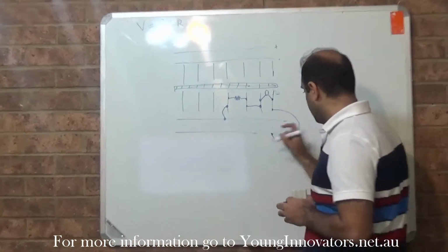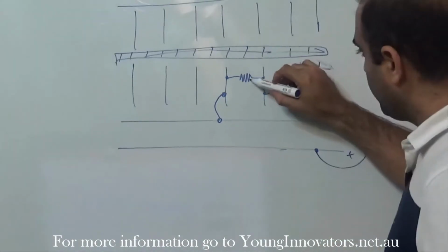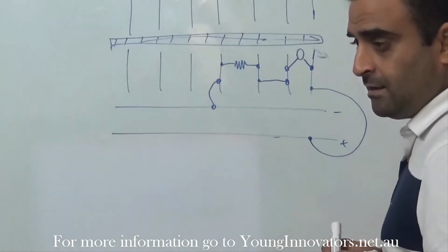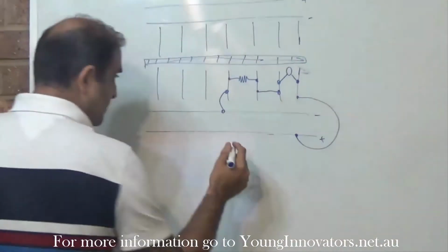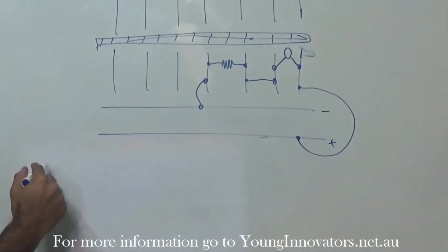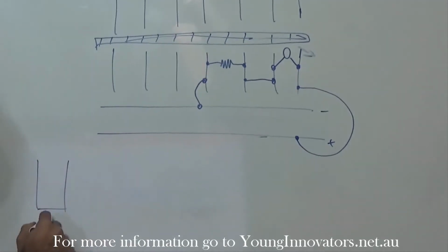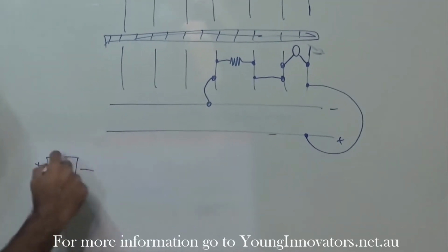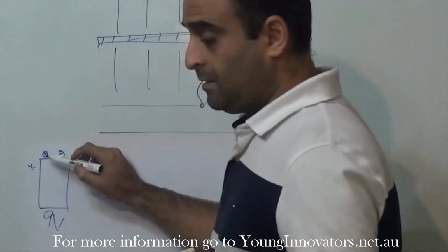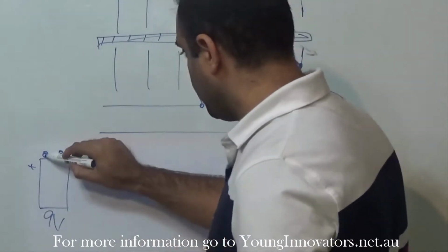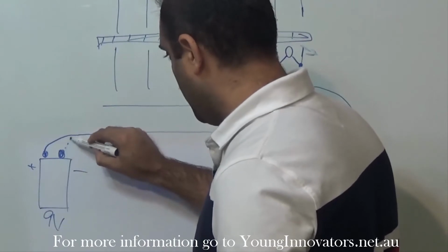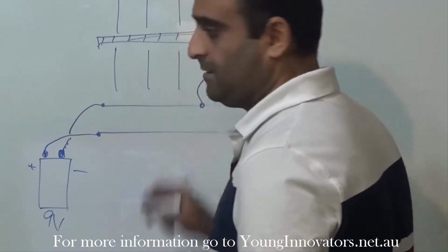Okay, and then, so what's missing? We have the LED, we have the resistance. What's missing? The power. The power is missing, right? So this thing doesn't have any power. So what we need to do is take the battery, the 9-volt battery. This is plus, that's minus. So where will the plus go from here? To the plus here, exactly. This plus will go here, and this minus will go to the minus here. And that's it.